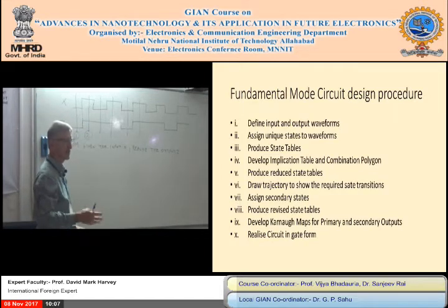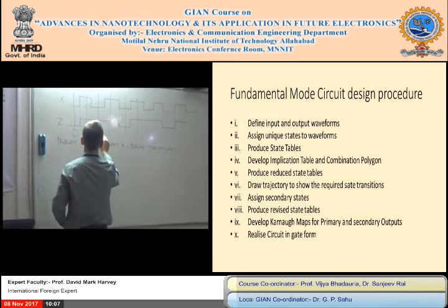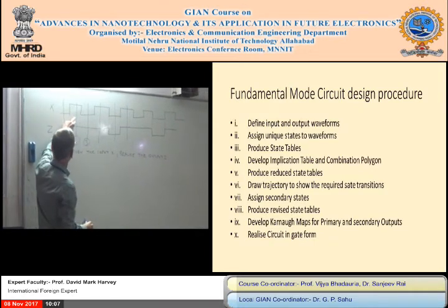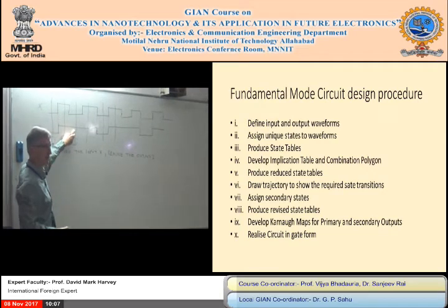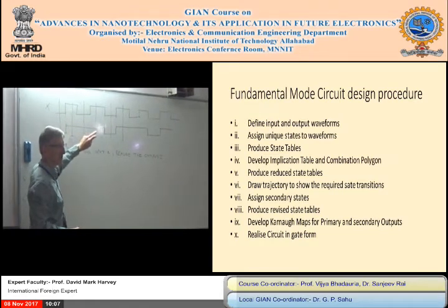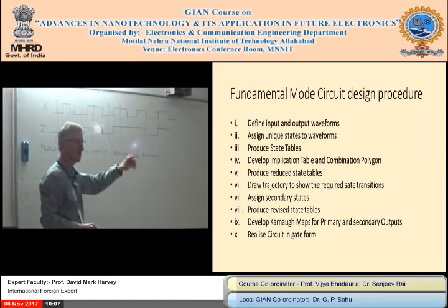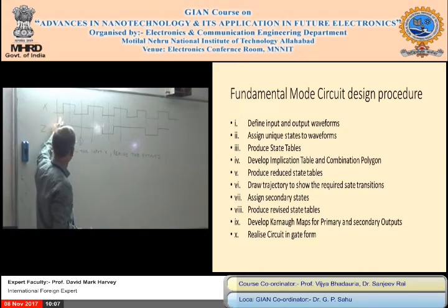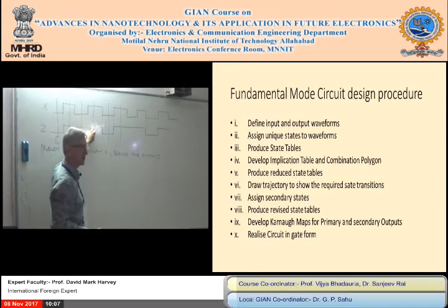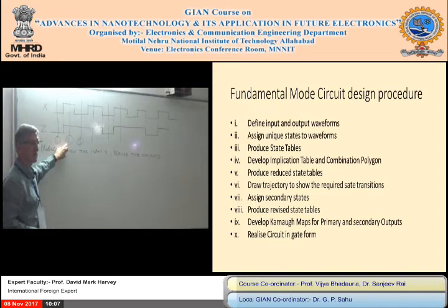I designed it deliberately, and it's not wrong that you got 3, don't worry, 100% in the UK will get 3. So you got 3, because the input's low but the output's high again. Now when I'm trying to think about these types of circuits, they've got memory. So what we're trying to do really is what my friend said there, we're counting 1, 2, 3, 4 half pulses before it changes. This state here, input 1, output 1, looked exactly the same as state 2.